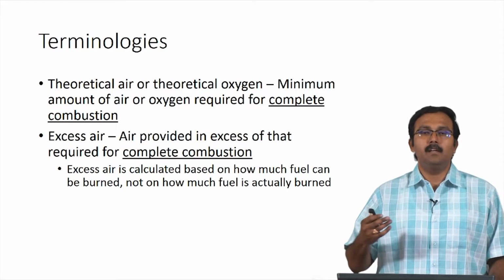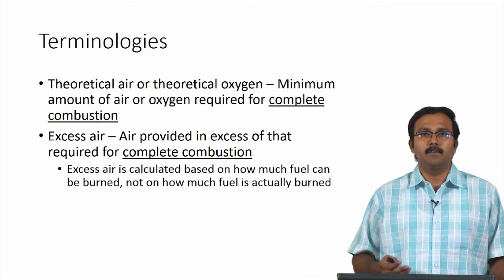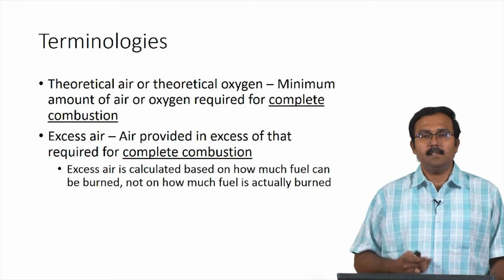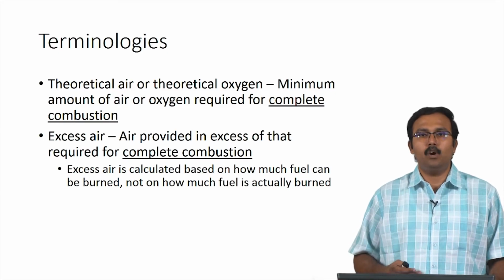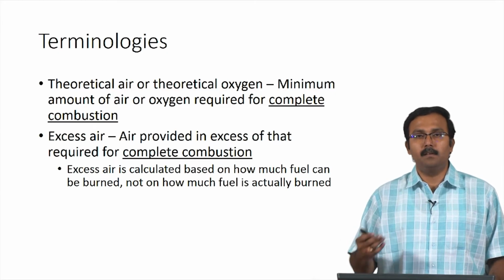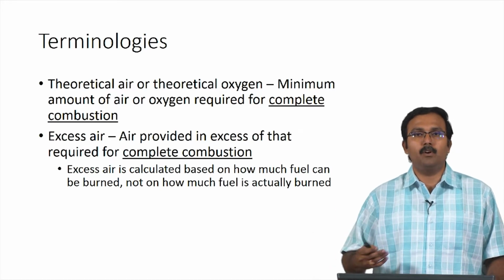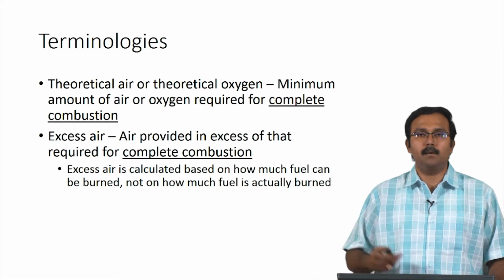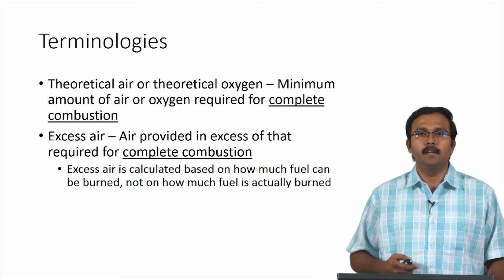So, thereby utilizing the most out of the fuel. For this reason, air is almost always supplied in excess. So, excess air is actually calculated based on how much fuel can be burnt, basically how much fuel is available for the combustion reaction, rather than how much fuel is actually burnt during the combustion reaction that is being studied.